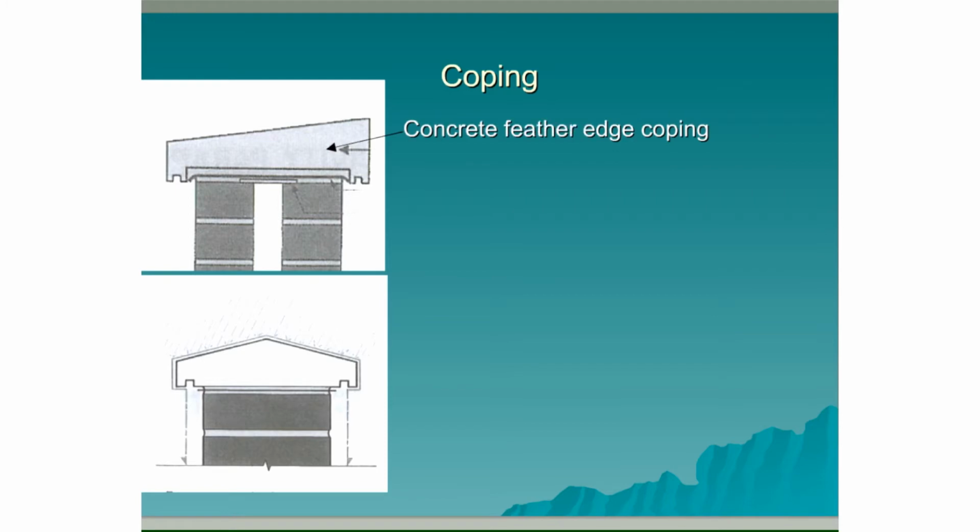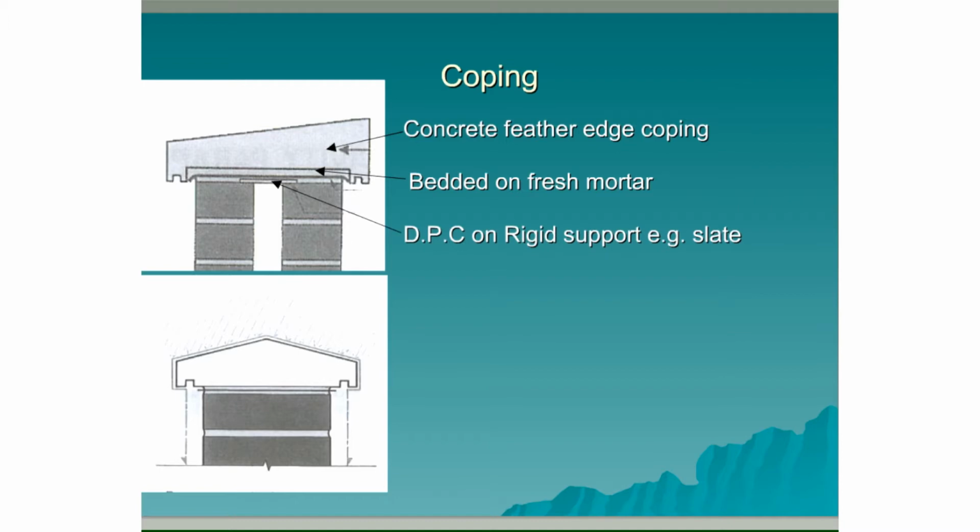A concrete feather edge capping. Bedded on fresh mortar. The D.P.C should have a rigid support underneath it, for example slate.